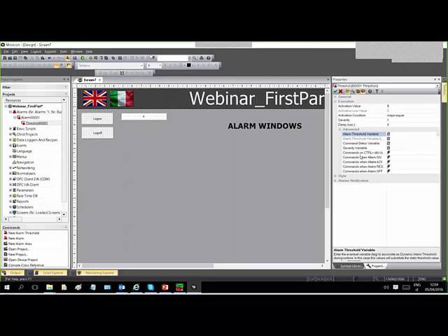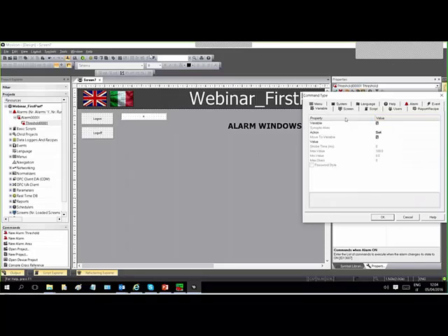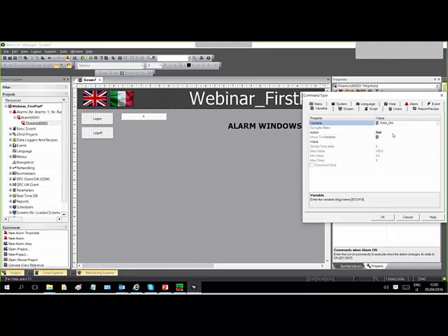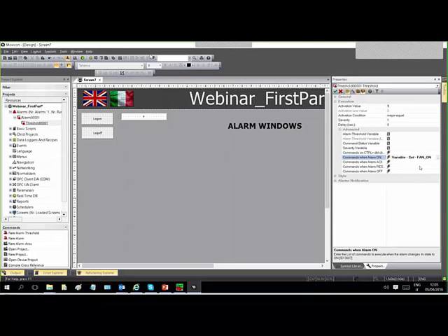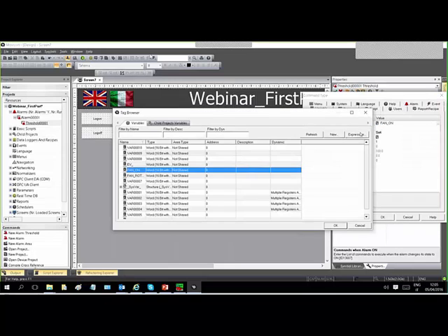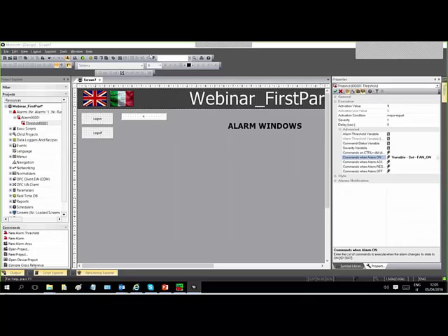You could perform commands when the alarm is on. When our alarm is on, say lube oil, I can start the pump by triggering a variable: set the variable fan on, set equal 1. I know, guys, this is logic that is normally done in the controller, but for some it could be interesting to have the possibility to perform this kind of small logic; it could also be an expression. To make a reaction when the alarm is on, perform an action. When you acknowledge the alarm, do another thing, and so on.